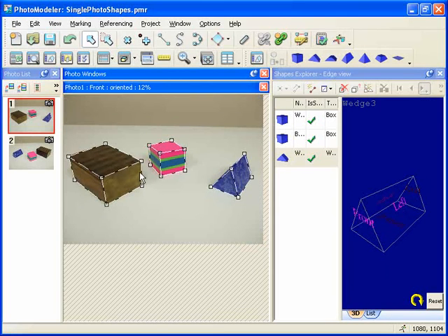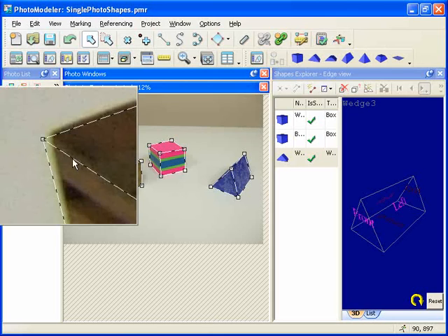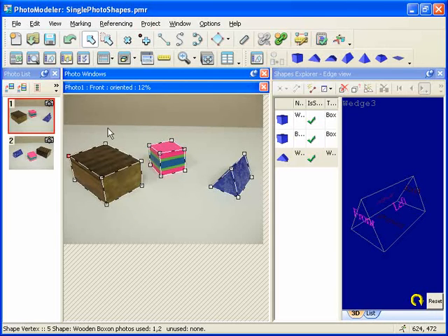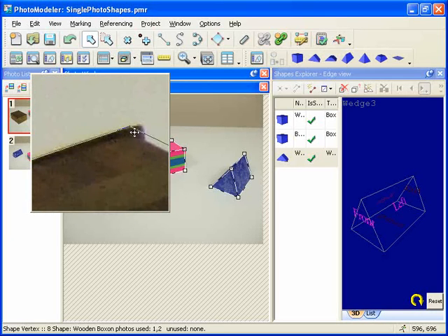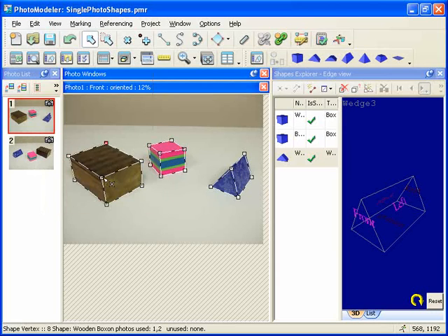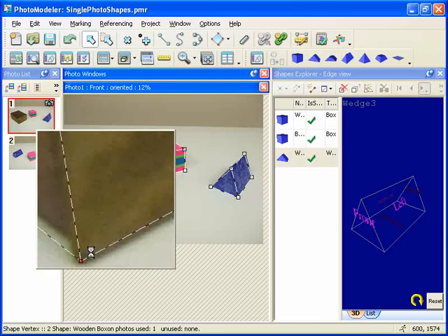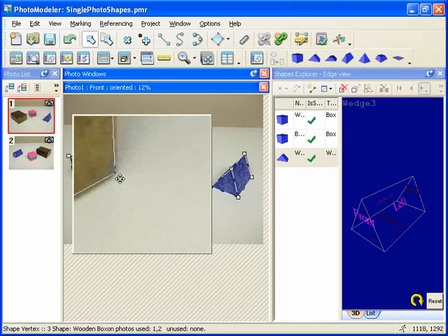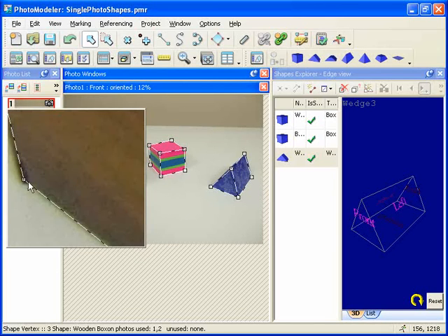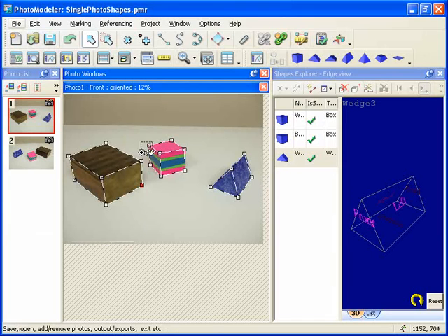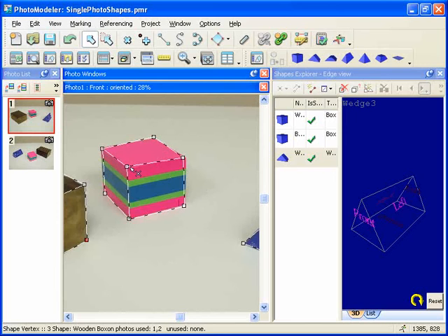We can review Photo 1. Again, we can use the Alt Zoom. Or press Control and hold the left mouse button down and drag a region to zoom that entire region.